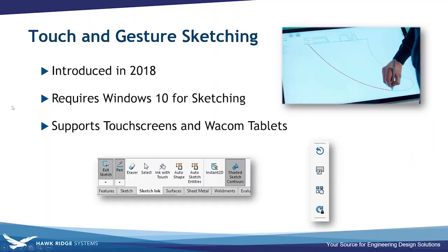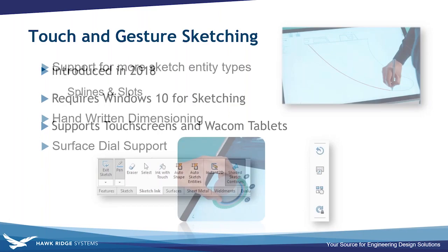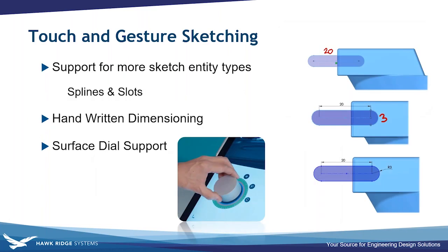So a touch interface was introduced in 2018 and has some great new enhancements in 2019. So a Windows 10 operating system is required for any touchscreen interaction inside of SOLIDWORKS. So you can now gesture your sketch slots, splines, and even dimensions. So let's take a look.